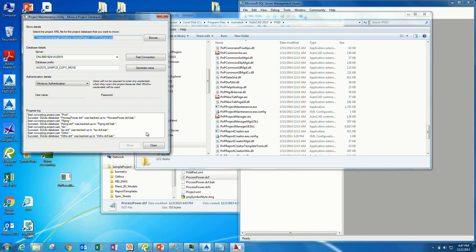The data cache file exists because P&ID doesn't always need to look on the server for data, which speeds up the process. But it can cause issues because the data in the local data cache may be old. Like I said, I don't know for a fact that it fixes these things, but it makes me feel a little better, and it might prevent issues you never know about. It won't hurt you if you don't do it, but it could benefit you if you do.